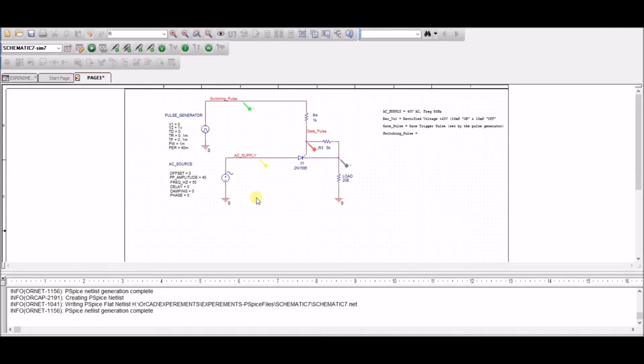So what happens when there is a sine wave generated and there is no voltage here? Ideally this should not conduct and there is no current flowing from the anode to the cathode, except for a few small leakage currents that could occur, could be in microamps. So let us take a look here.